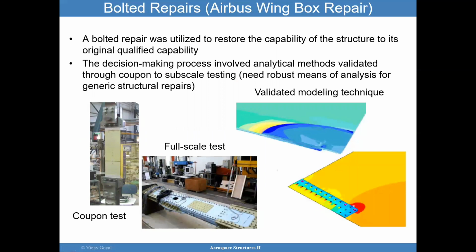It's not always possible to proof test a repair, but it is always possible to qualify the repair and ensure that the repair is a good one through coupon level testing, full scale testing, and using modeling to validate these repairs. So really, a bolted repair can be utilized to restore the capability of the structure to the original qualified capability. And so the decision-making process does involve analysis at times, and so that's why it's important that you validate